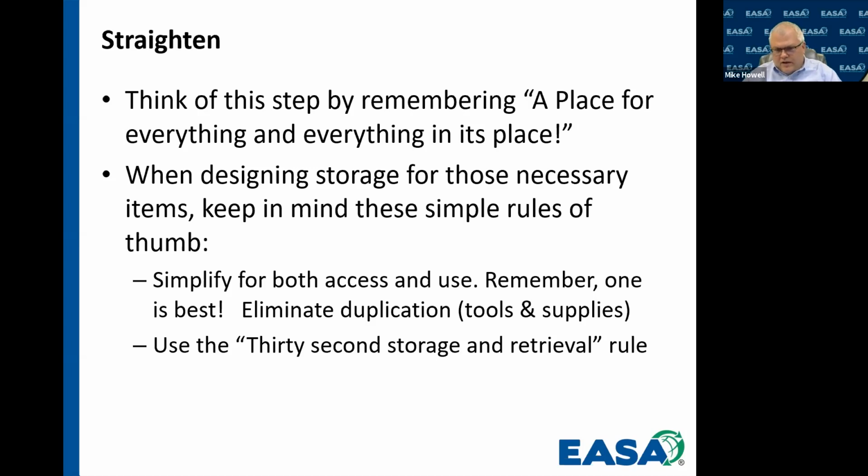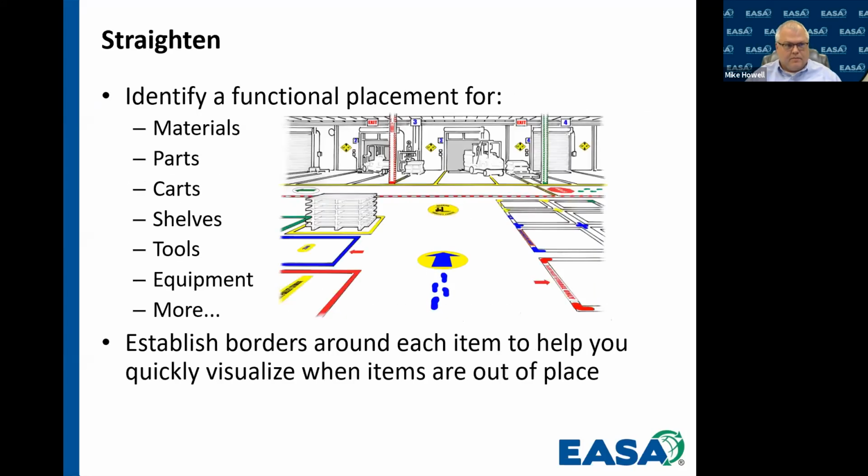Just remember to organize your storage according to your frequency of use. Things you use most often, keep those closest to you. Everything accessible within 30 seconds. And if you have to walk outside of your work area to get an item that you use regularly, if you find yourself having to walk across the shop, then the item's located too far away. And that's where we look at layout issues with this type of process.